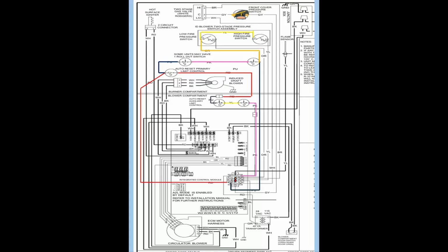A control module performs a gas valve circuitry check. As you see now, you've got power up to your main and your low fire and your high fire. Because the pressure switch is open here, your front cover pressure switch, the valve couldn't open anyway, because remember, a valve coil is a load, and a load has to have a complete path, from the hot leg all the way through the load and back on the neutral.